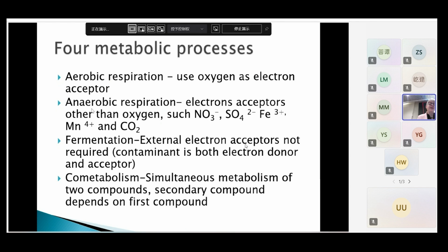So yeah, high permeability, and just make sure that you have sufficient nitrogen, phosphorus, and other things. Again, you can do a treatability study if you don't know whether that particular compound is biodegradable or not. So you can add various things and do some monitoring.